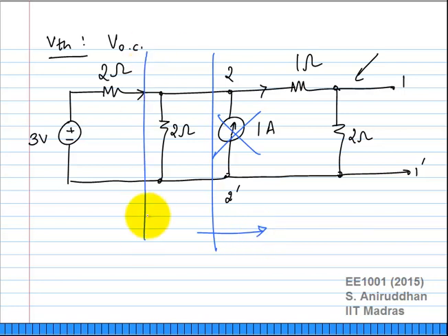And on this side, what do I have? I have 3 ohms in parallel with 2 ohms. Okay, so I can find out the input resistance across these 2 nodes. Then I can find out this current Ix. I'll call it Ix1. The minute you know Ix1, you can figure out how it splits among a parallel combination of 2 ohms and 3 ohms, right? So the fact of the matter is, you will need to practice solving these kinds of networks.